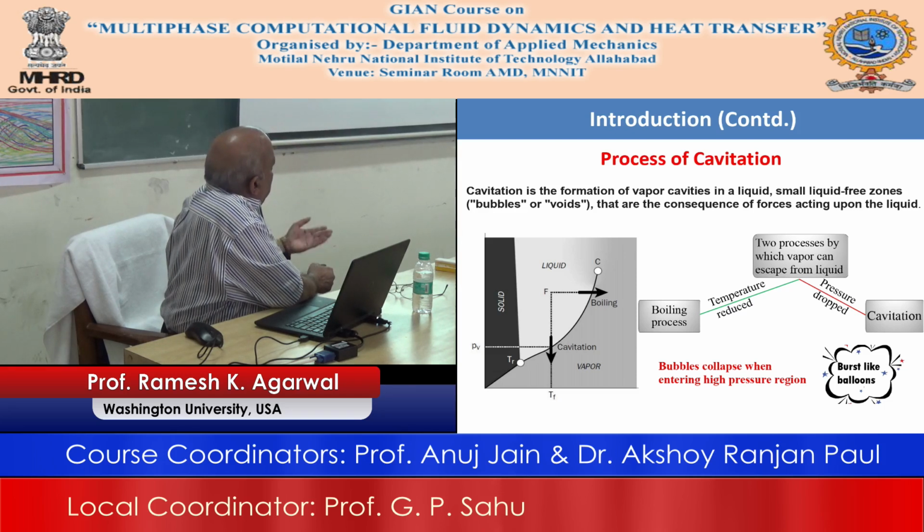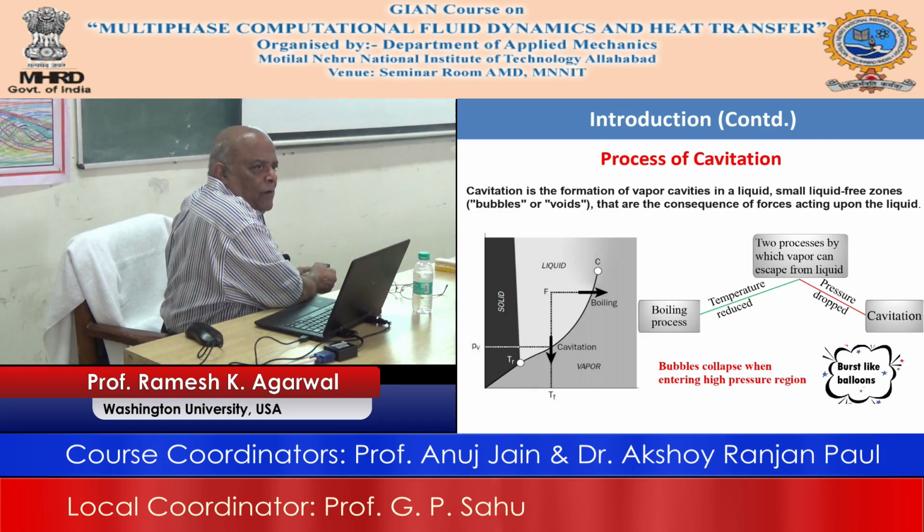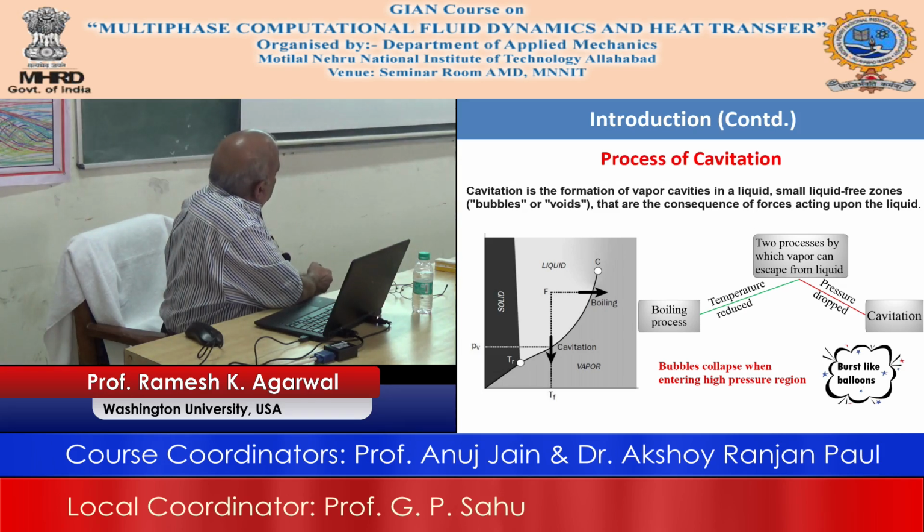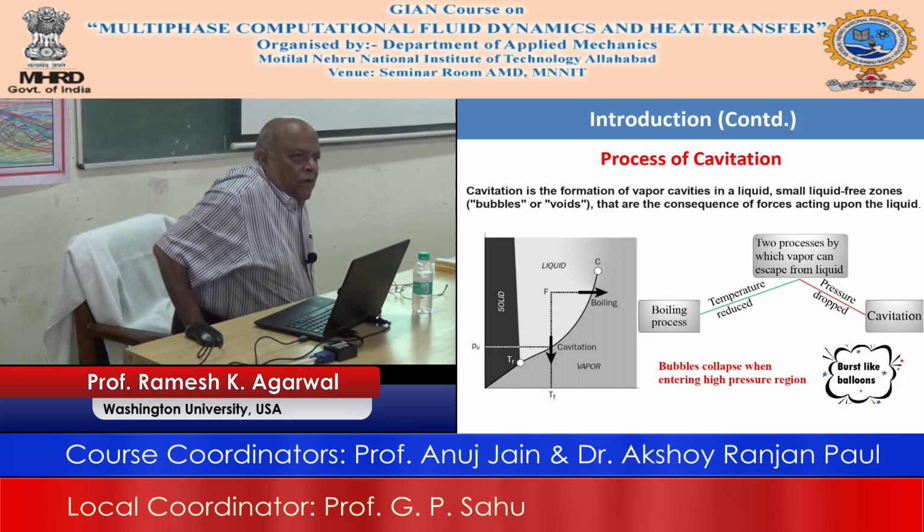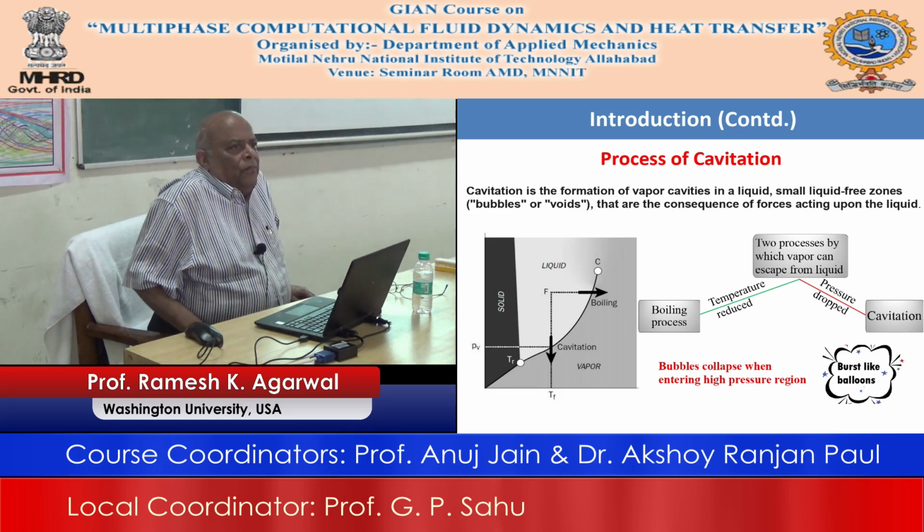Now, as I showed you, the bubbles occur because of the low pressure, right? And then they can move and enter into the high pressure region on the same blade. Then they will burst, and when they burst, it can cause impact, and that impact can result in erosion. Similarly for the boiling process, but that is not the subject here. What we want to know is how we can model, using Fluent, the effect of cavitation. That is the goal, and you can do it.